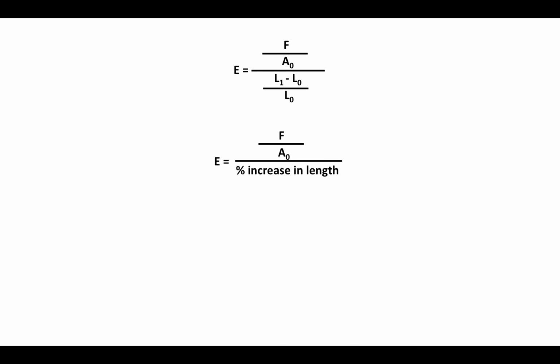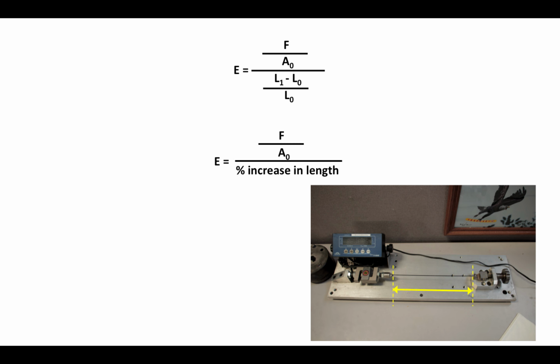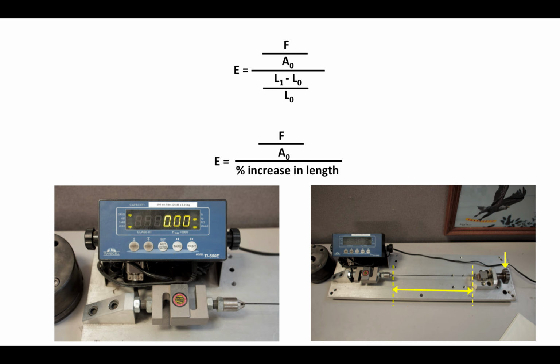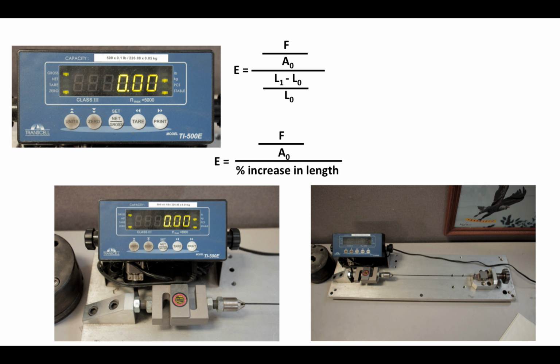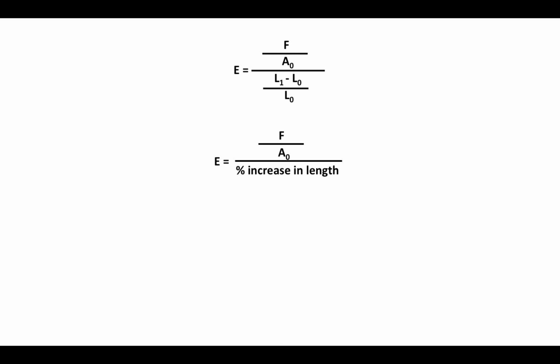Using this device here, I can put a spoke in it, measure its length, and then add tension to it and measure its length again, and then read the force applied over here on this gauge. In this particular device here, I can crank this up to 5,000 newtons if I want to, which is enough to exceed the tensile strength of the spoke. I have the capability now of measuring the elastic modulus of any spoke, of any material, of any diameter.